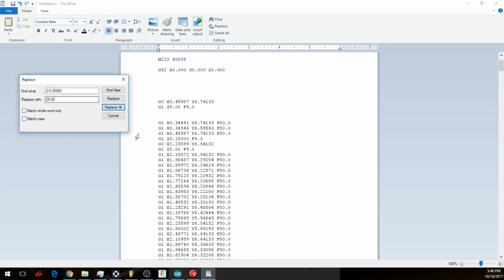Okay, we're all good. And now, as you remember, we have 0 as the height that we're translating in, versus Inventables wanting you to go up a little bit. So instead of having it be 0.15, we want to change it to 0, because we set 0 as the height we want to translate in. We're going to replace all.